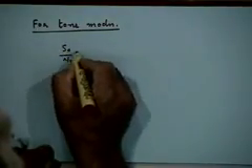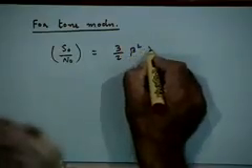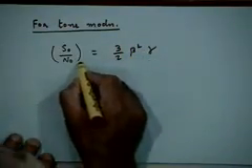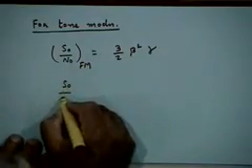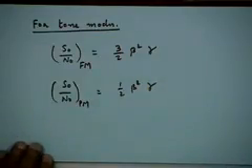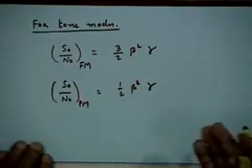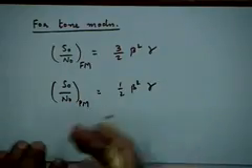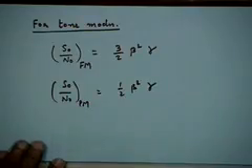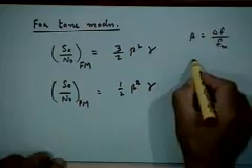So for tone modulation, you can check that the expressions for the output SNR reduce to these very simple expressions: 3/2 beta square gamma for the case of FM and half beta square gamma for the case of phase modulation, where beta of course is your modulation index, defined as the ratio of peak frequency deviation to the frequency of the modulating sinusoid. Remember, beta is delta f by fm.